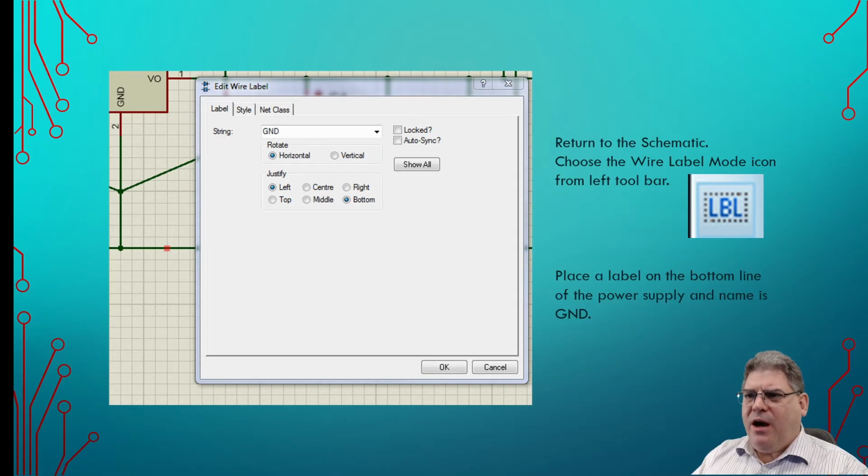So once you're done, the next thing is that we want to go in and add a wire label. I mentioned that we deleted the ground from our power supply. What we need to do now is actually add a wire label. Okay, so in this case, we're going to call it ground, and it means that the wire is going to act like a conventional ground. So just play along here.